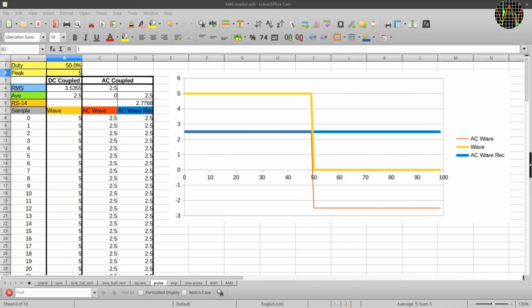This is a pulse, and the only difference between the previous waveform and this one is that instead of switching between positive and negative amplitudes, this one switches between positive and 0. This waveform is quite important as it's used a lot in pulse width modulation. But since the multimeters are AC coupled anyway, for them this wave looks exactly like the square wave before.